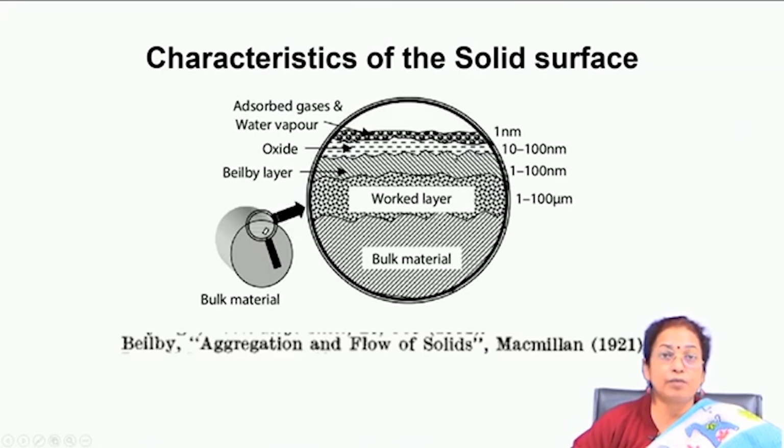It is called the Beilby layer, because its structural features are exactly vanished on the surface, because of some cold working operation which the surface has undergone prior to its processing. So, this Beilby layer is very important and it is amorphous in nature, and the presence of this layer will be visible if you do Auger electron spectroscopy, X-ray photoelectron spectroscopy, or maybe low energy electron diffraction analysis. You will get to know about the amorphousness of this particular feature.